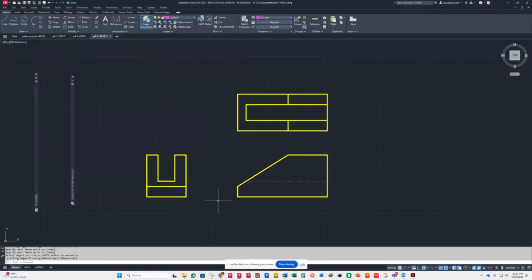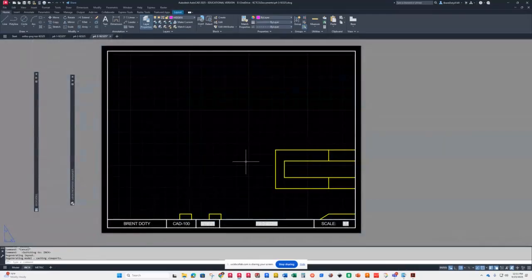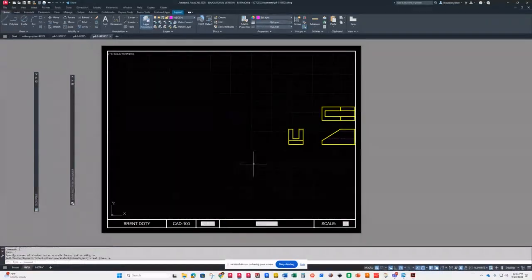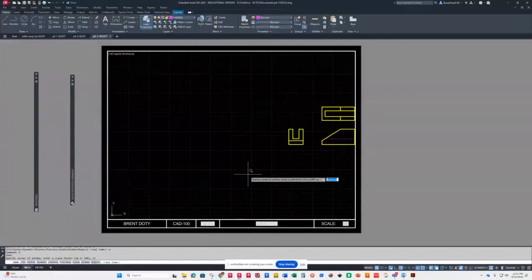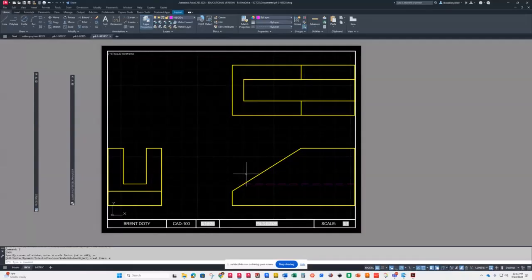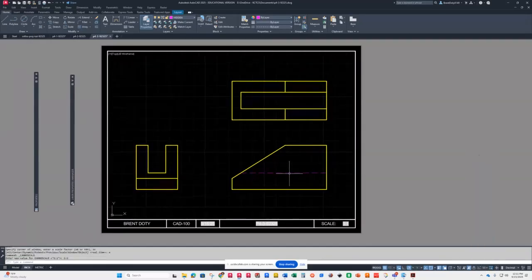So anyway, this is an inch drawing, so we'll go to the inch layout, activate your viewport, zoom all. Okay, what happens if I do zoom extents? There we go. Zoom extents works better. So we did zoom, Z, enter, E is in extents, or Edward, whichever way you want to go. And now I can change my scale to 1 to 1, and I don't have to move it. It's centered for me. So extents is kind of nice. It kind of centers things up.